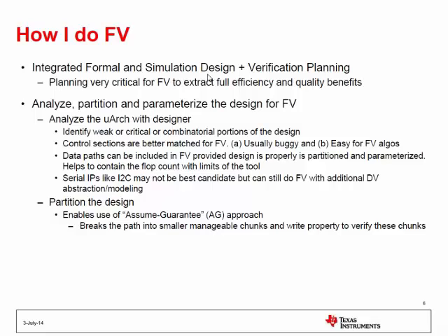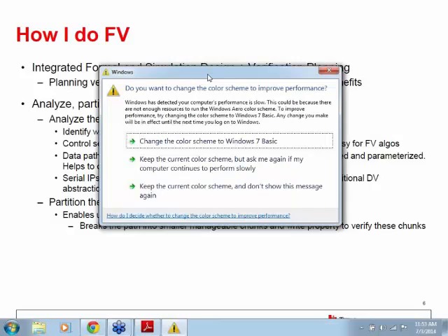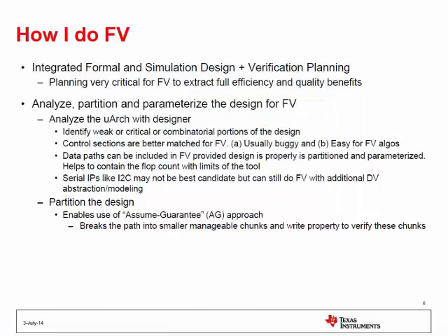So I just work with him and then have some blackboard sessions and try to understand how the whole microarchitecture is structured, and then see how I can partition the design so that I can write assertions that are manageable. You can still write a very complex assertion that goes into 5 or 6 lines that will go from your input to the output of the design, but you'll make a lot of mistakes in it and you'll spend a lot of time trying to make sure those assertions come out correct. So you need to actually pipeline your assertions so that you manage and solve simpler problems, but at the end of the day, if you look at it from a top level, you see that the whole problem is getting solved.